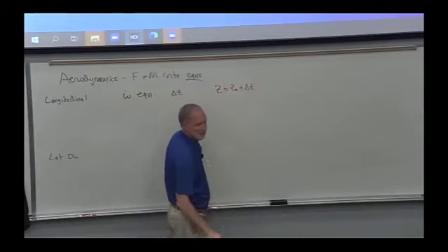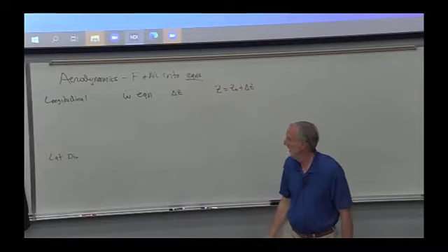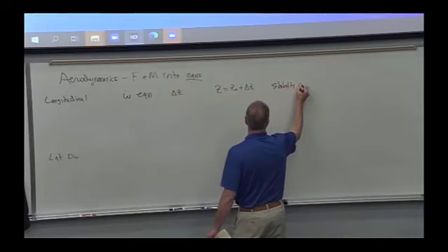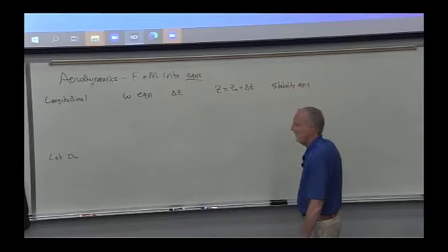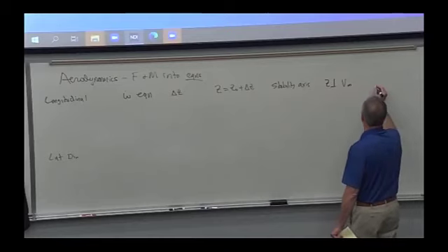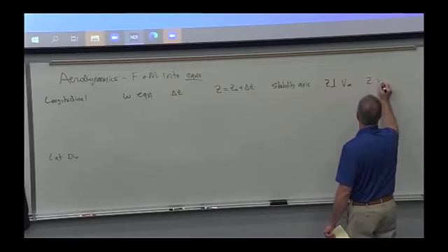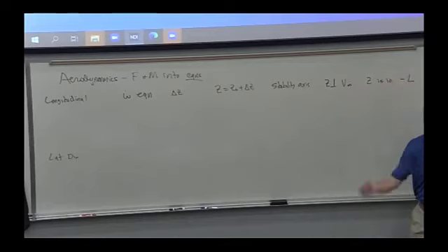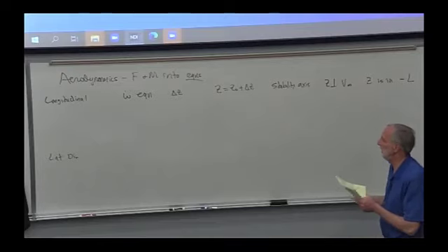it's the small perturbation part of the total force Z. And because we chose stability axis, Z is perpendicular to V infinity. And so that means that Z is in the minus lift direction, right? Z is down, lift is up, lift is perpendicular to V infinity up, Z is perpendicular down, and so that makes things really easy here. That's one of the reasons that people use stability axis.